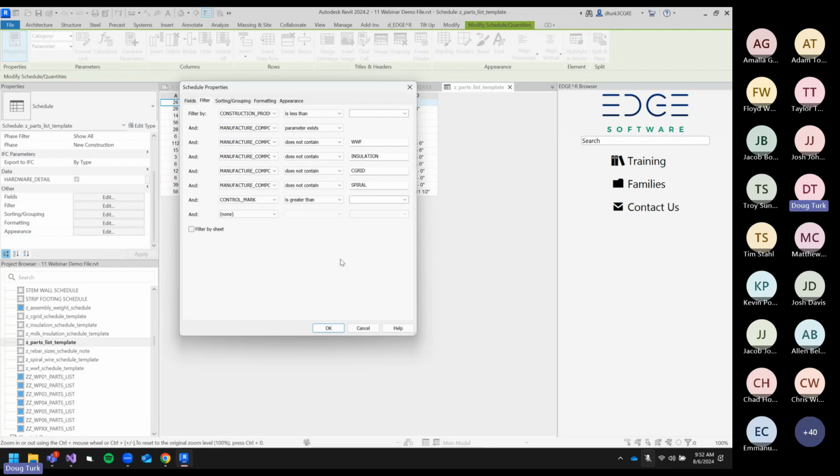That is something that was not present in 11.0.0. So if you guys ran the project shared parameters utility on that release before the hotfix that just came out, you might have seen some strange behaviors when you tried to run auto ticket or the ticket populator, because it was filling up that last filter and blocking you from being able to add that construction product host one. Just make sure that you look back at any models that tool might have been run on in that specific release before this hotfix to make sure that everything's correct there. And we apologize for that mistake, but it's fixed now, and everything going forward should work correctly there.